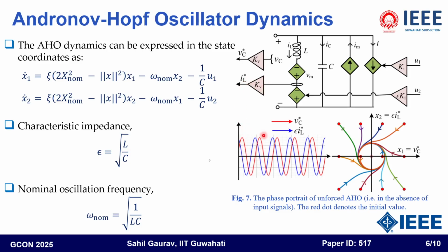These orthogonal signals are used to generate the PWM pulses, and we can use them as the alpha-beta signals. Then the alpha-beta signals are transformed into ABC signals, which are the modulating signal, and the modulating signal is given to the PWM generator, which ultimately provides the gate pulses for the converter.